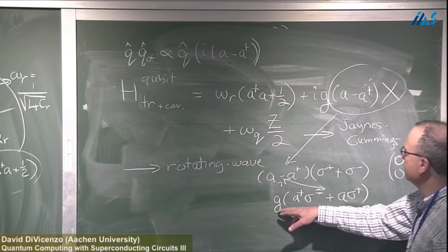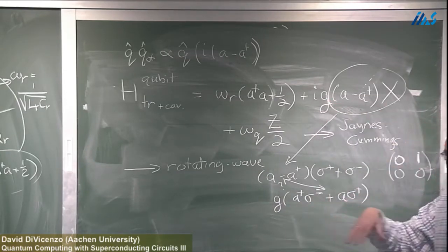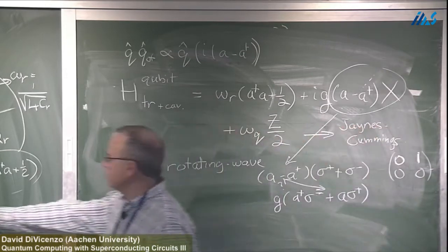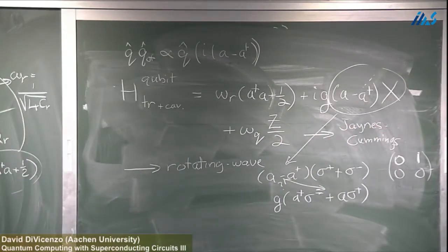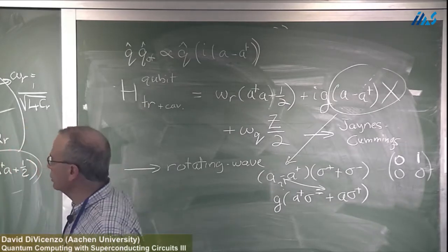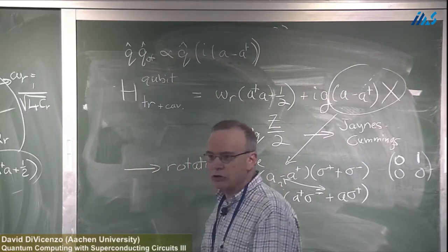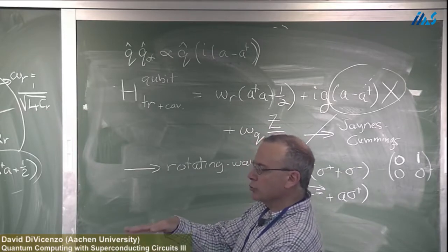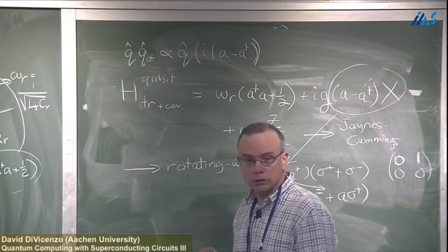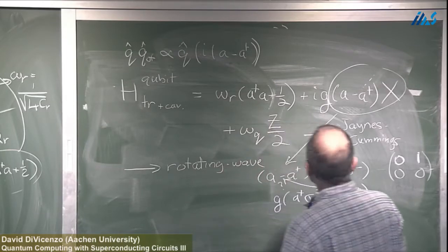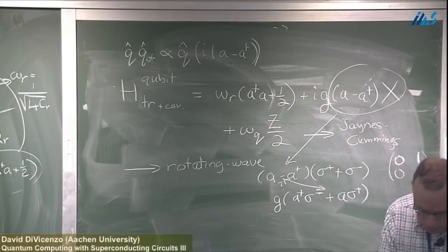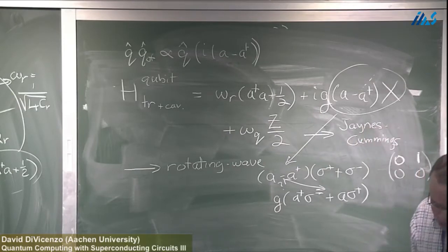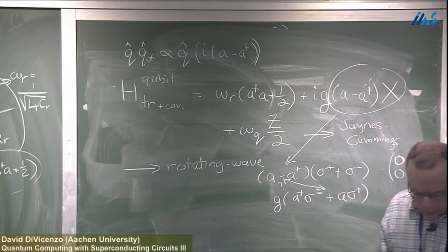Now, this g is a traditional notation for an atom cavity coupling. You can see that it was, in fact, proportional to this coupling capacitance. So the way you make g bigger or smaller is by changing the geometry of the thing that I just erased, of just having the capacitor, the transmission line metal and the transmon metal closer or further away will affect that. It's just simple geometry. And it can, in fact, be put into regimes that are very, very nice for qubit behavior. In particular, this sort of strong coupling regime is quite easy to achieve.